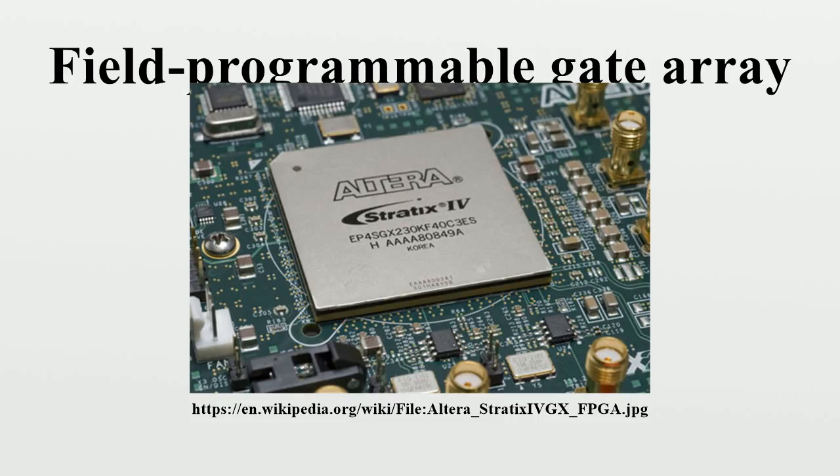FPGAs can be used to implement any logical function that an ASIC could perform. The ability to update the functionality after shipping, partial reconfiguration of a portion of the design, and the low non-recurring engineering costs relative to an ASIC design offer advantages for many applications. Some FPGAs have analog features in addition to digital functions.